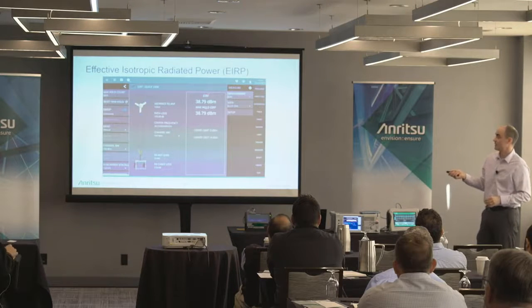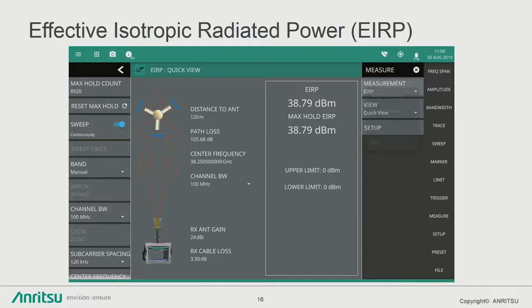This is the number that I'm concerned about, right? If I put the antenna up and I go out there today with my directional horn antenna, and I'm directly on that bore site, directly in the center, these numbers are going to be the same. If a storm had gone through or some other thing had bumped that antenna, then when I'm here, I should be in the center, but it's not, and I'm going to have a lower number.